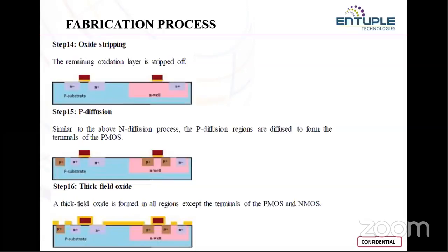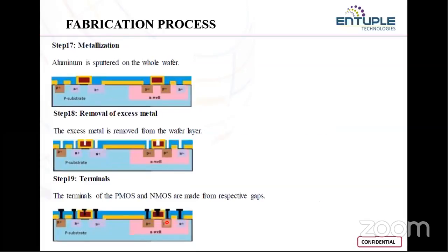After you form these things, you again create a thick oxide layer, because after this you'll be getting your contact points. So for getting these things, you are just inducing a thick oxide. Over that thick oxide you get the aluminum, aluminum on that material.